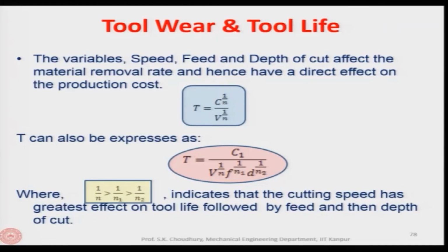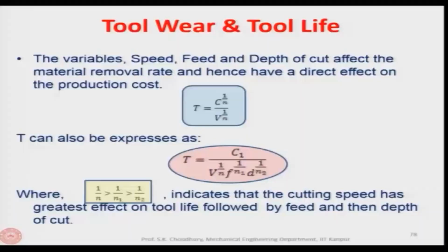Okay. Here what F. W. Taylor has shown is that T is dependent on the cutting velocity. But apart from the cutting velocity, the tool life also depends on the feed and the depth of cut in the following way, as shown here. This can be found out experimentally, and after Taylor's tool life equation was invented, further research took the feed and the depth of cut as variable parameters, experiments were made, and this is the result which has been found.